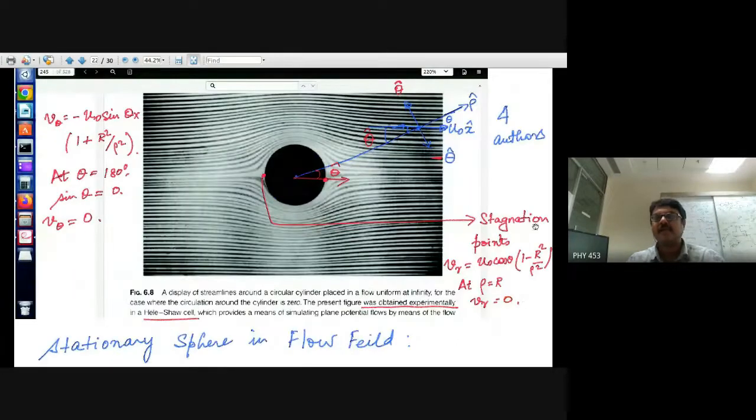Well, it will. So basically what you have is u0 in the x direction, and when you take cos theta, Vr equal to cos theta, so this is theta. So this is the radial direction. If you take the component of u0 in this direction, cos theta, that will give you the velocity in the radial direction. Remember, z is into the plane of the screen. Moreover,